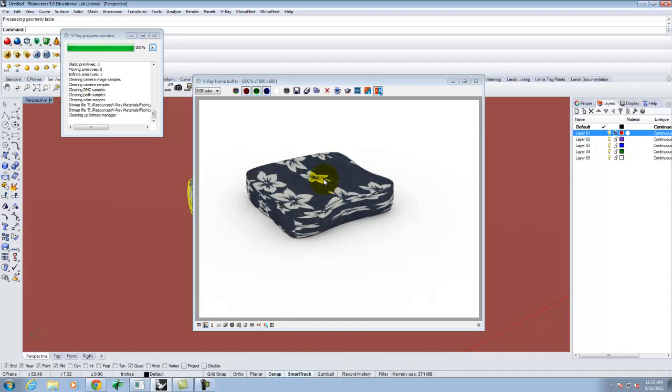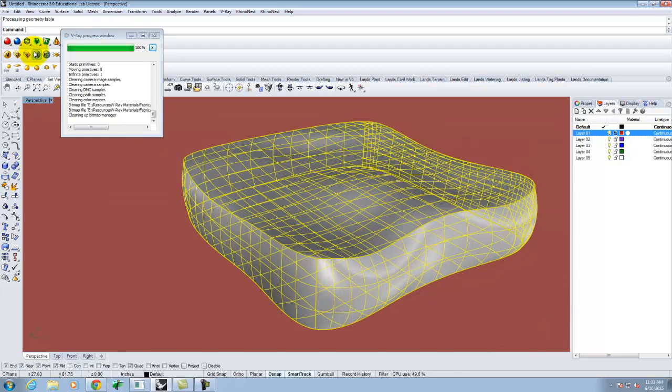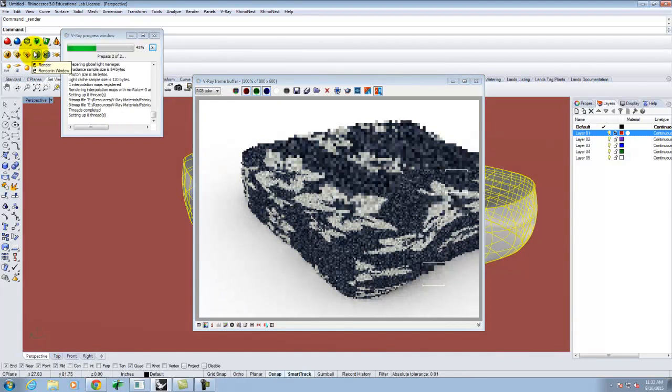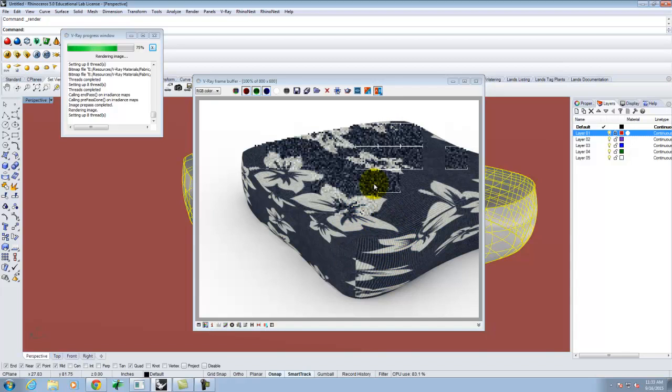And we can see that I have something that looks reasonably like a cushion. There's still always fine-tuning. So we have this, and we look at it. I'm just zooming in a little bit. I have a fabric that's going on the top, and it looks reasonable. I have a fabric that's going on the sides. But the texture mapping doesn't really match. Obviously, this doesn't look anywhere near what the top looks like. The texture's too big, etc. So we need to do some adjusting.